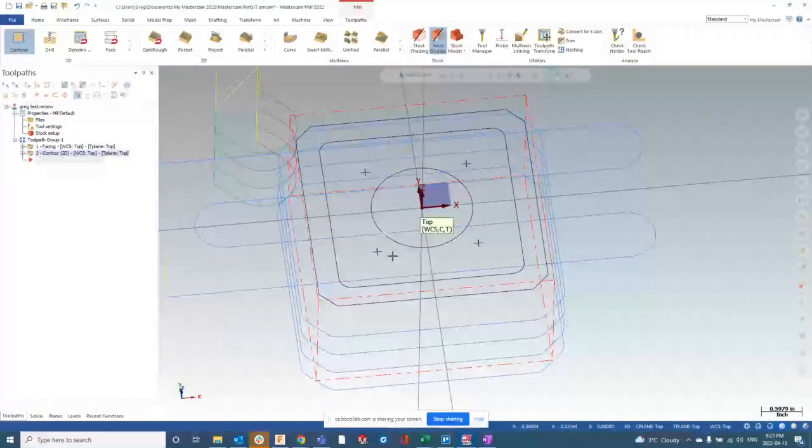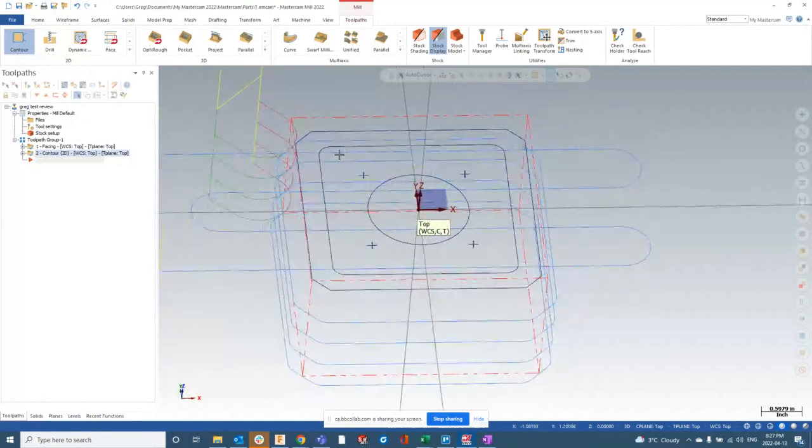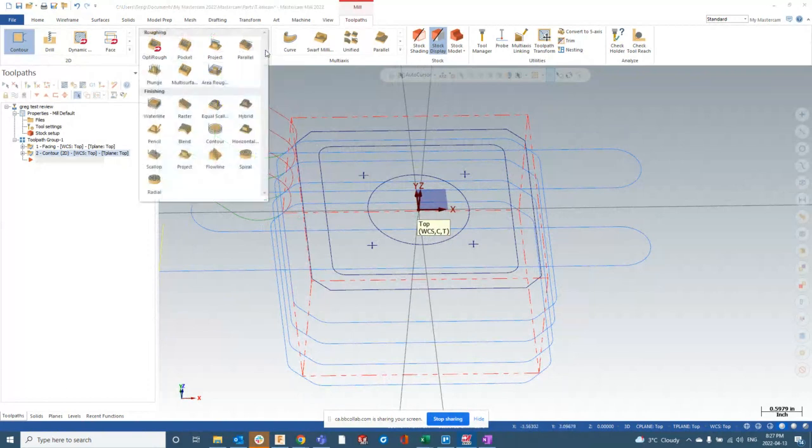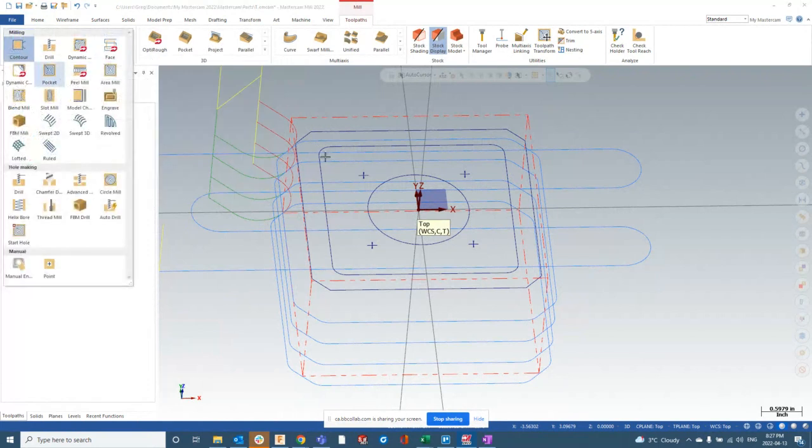Good job. Okay, let's do these next pockets, and the way you want to do it is probably cut the shorter pocket first, and then the pocket that goes all the way through. Okay, so let's do that. Let's cut this pocket. I want to see you guys using 2 different operations, okay? I want to see you use your pocket milling for the square pocket and then the circle milling for the circular pocket. And this internal pocket, this one could be a square or this one could be a circle. It might change, right?